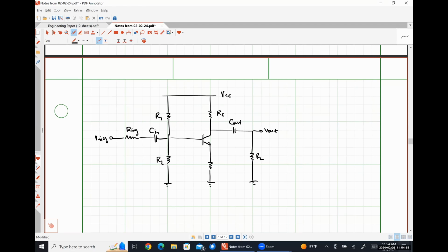So this is the circuit that I drew originally when we were talking about common emitter amplifiers. And this is the one that I said we were going to skip doing any formal analysis of, because we effectively already know how the amplifier portion of this thing works. Okay. So what we saw when we included some emitter degeneration was, just to recap, an increased input resistance, roughly the same output resistance, and a decrease in the voltage gain.